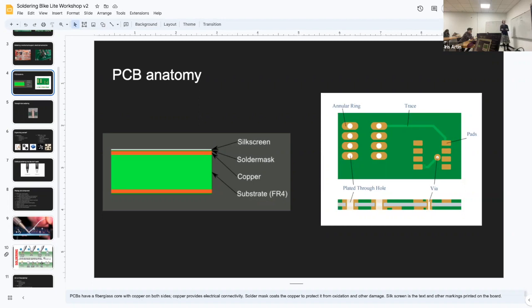And to answer the last question about why we cannot do this on the CNC mills that we have here: these boards are very thin, and as a result, they are somewhat flexible. So when you put one of these boards on a CNC, there's going to be some amount of flex in the board itself. The thing that PCB mills do that general purpose mills don't is that they can follow the surface of a board that might be slightly warped, rather than assuming that the surface is perfectly flat.